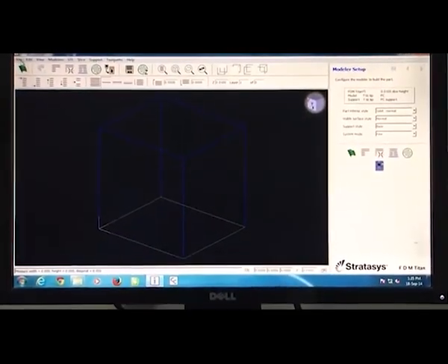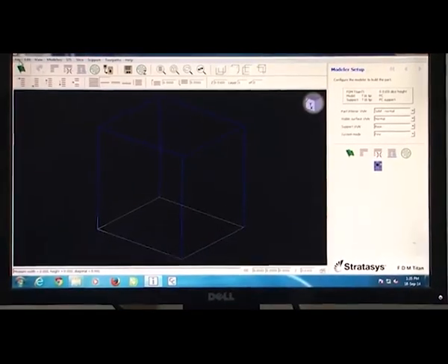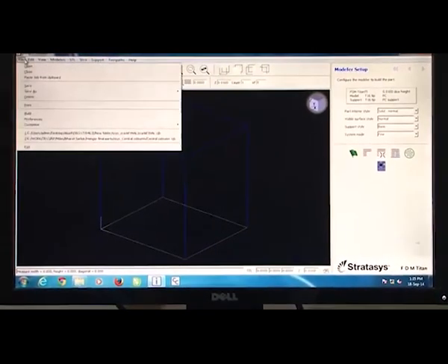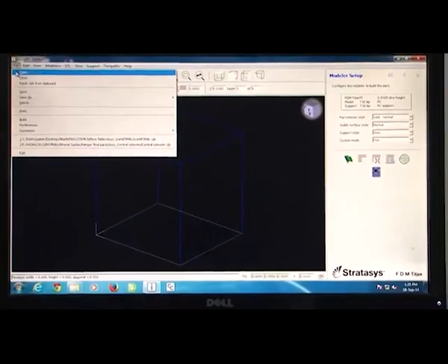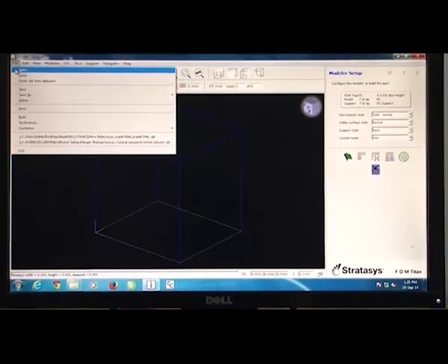So, we actually go to the file menu, and in the file menu we actually can open up a file. So, here what I have done is, in the interest of time, I have actually made a CAD file earlier or borrowed it from some source, and typically this CAD data has to be saved as a .stl format for enablement of this Insight version 9.1 software to be able to read it. Okay, so therefore, the STL file has to be somehow opened using this Insight software.